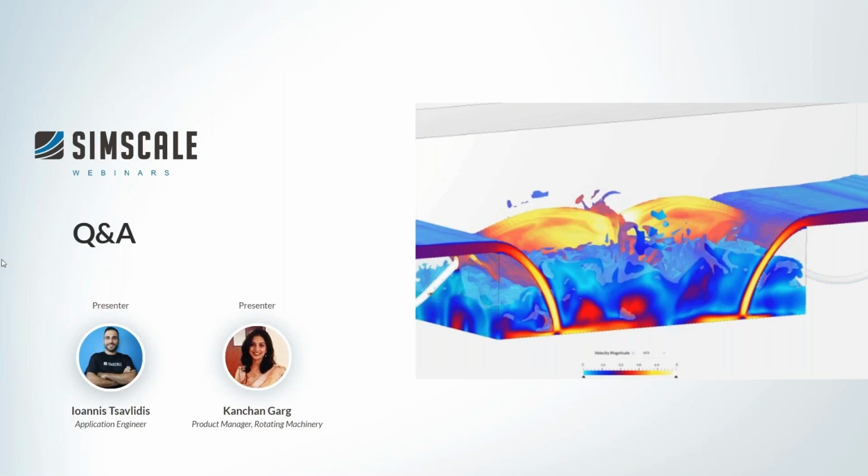And because it's a binary tree methodology, what it also means is that from one mesh cell to the next, the aspect ratio is very good. It is 1:2, as against most other hex meshes where you may even have an aspect ratio of like 1:8. I hope that answers.